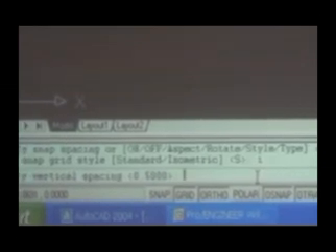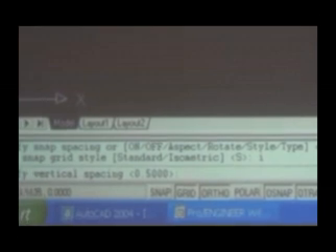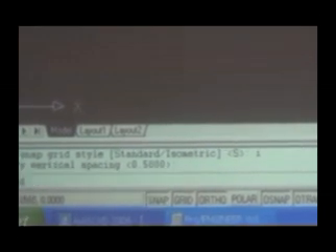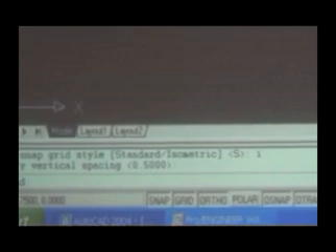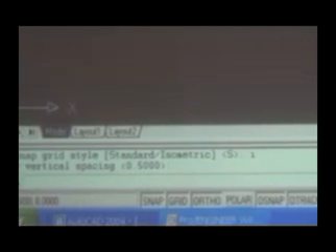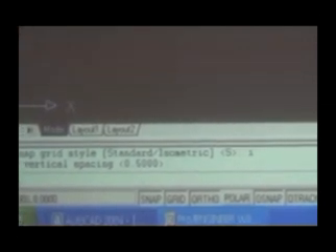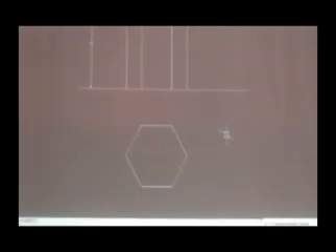Now you see the vertical spacing, it is also here. You see this icon, the prompting icon, it is in an isometric plane. The icon itself is shifting. For that you have to go for the snap command. So from a standard two-dimensional plane, I can snap my icon to an isometric one, and from here I can draw isometric lines.